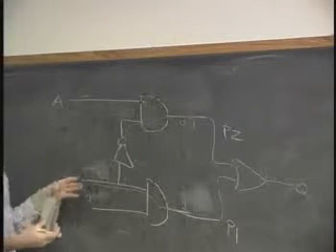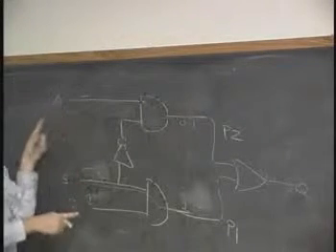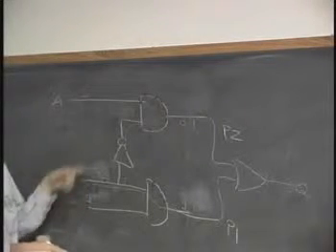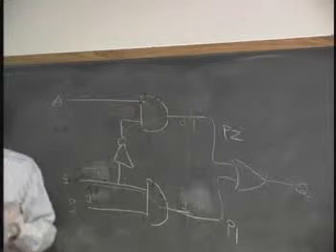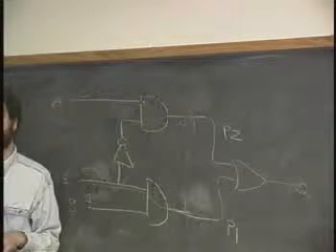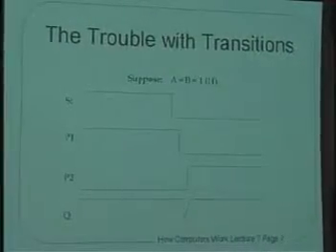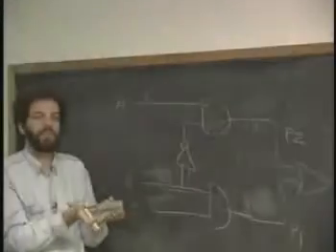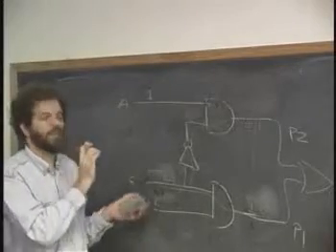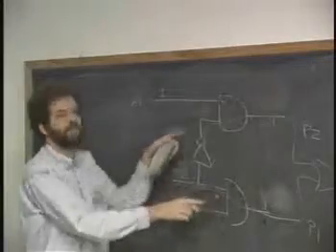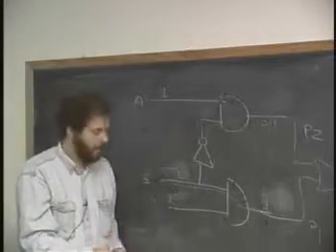And so a selector given 2 inputs, A and B, both of which are high, which is told first, choose B, and then next, choose A, may go through a transition where Q, which you see over there on the board, goes from high to low and then back to high again very, very quickly, as the internal circuitry of who's in charge of holding this output up goes through what's called a timing race. Okay? There's a race between turning this guy off and turning this one back on.